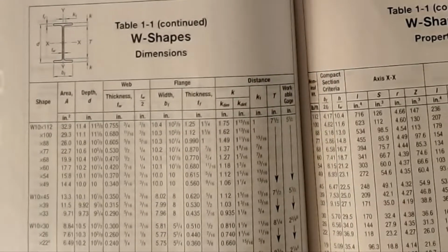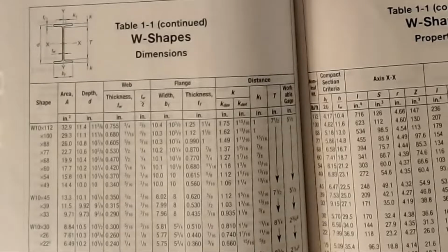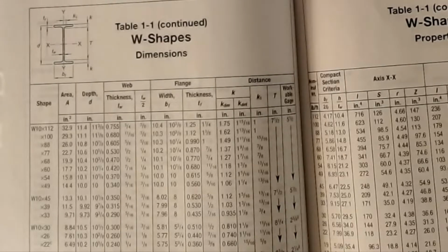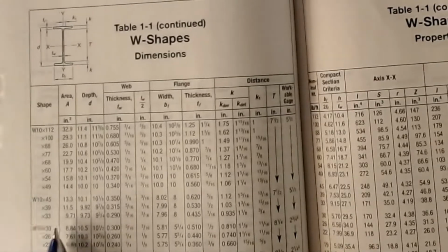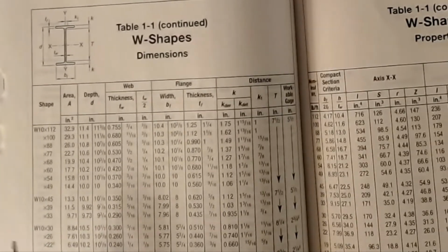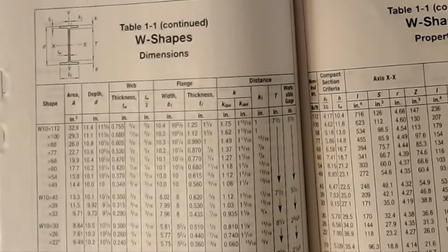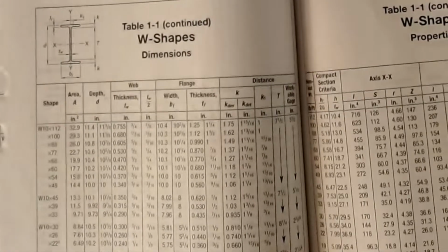And so instead of having to go calculate moments of inertia or areas, by me simply specifying that I need a 10 by 33, I'm guaranteed to have an area of about 9.71 square inches. I'm guaranteed to have a depth of about 9.73 inches, and it saves me a lot of information even on the drawing. So you'll see, as an engineer, we'll label a beam as a 10 by 33. Or maybe it's a column that's a W12 by 50 something or whatever it is. It's a very concise way of representing a whole lot of information because of the use of this book and these labels that we have here.